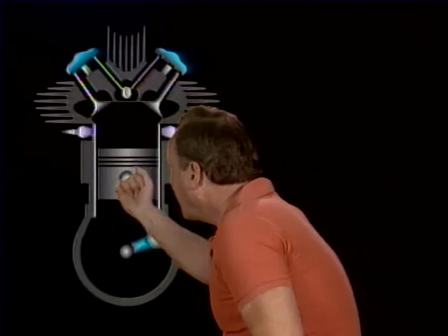They're going to say, let's assume you're checking compression with a differential pressure tester. And can you do it then? The question they're going to ask you is, can you do it with the cylinder at bottom dead center? What kind of reading would you get? The answer is you wouldn't get any reading at all.